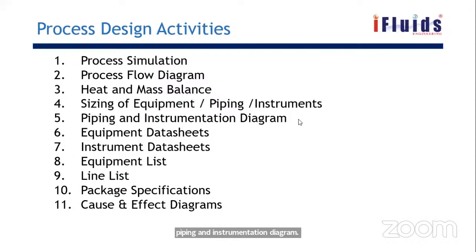This P&ID is the master and mother drawing for the entire stage of the project. That means from the design stage till the construction, and then the commissioning, and then the plant team who is handling and operating the plant. After the plant runs for 2 years, 3 years, they will go for a shutdown. At that time, they will refer to this P&ID. It is the mother drawing for the whole project and the whole unit. It covers all the piping, the equipment, and the instruments, everything at the site. After the design stage, this will be the input to the other disciplines.